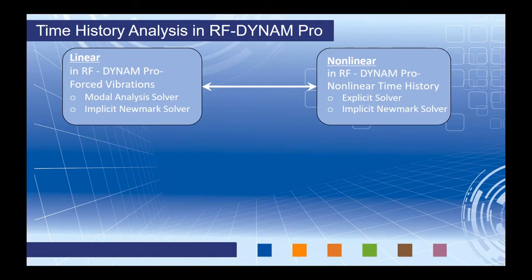Now, again, nonlinearities in the model are replaced, as I've already mentioned, with tension-only members, but also with compression-only members and with cables. They're all replaced by truss members. And by the way, a truss member in RFEM is nothing more than a typical beam element that can take both tension and compression. All we've done is release the moments. Now, other nonlinearities may be completely ignored, such as support conditions.